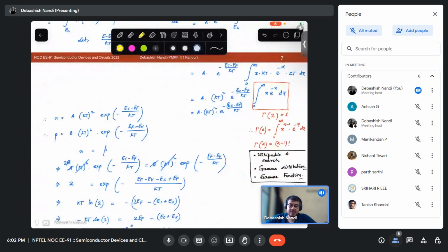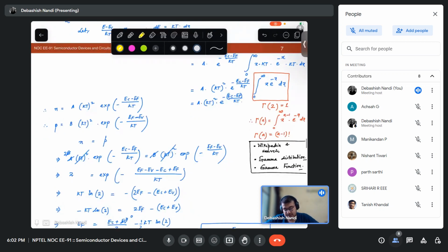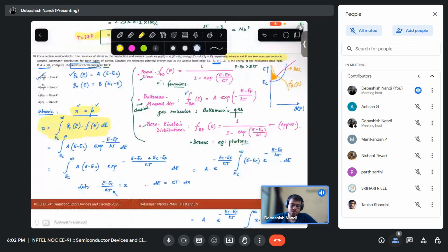It may not look simple at the beginning because gamma functions are involved, but take my word that there are much more difficult integrations. If you did not take Boltzmann's approximation here, you would go to Fermi integration, and those Fermi integrals are very terrifying. So for your course, do not attempt to solve this with Fermi distribution. You go with Boltzmann approximation of Fermi integration or Boltzmann distribution.